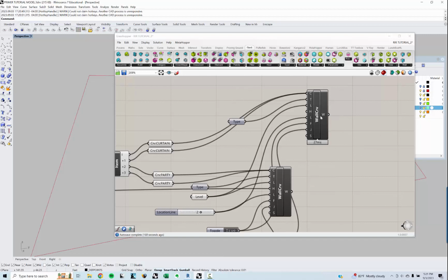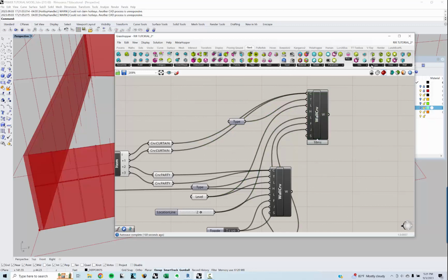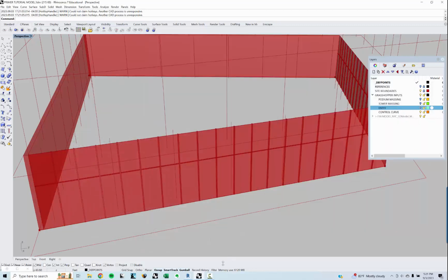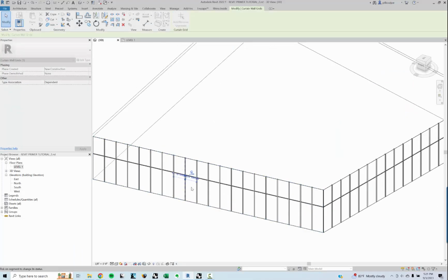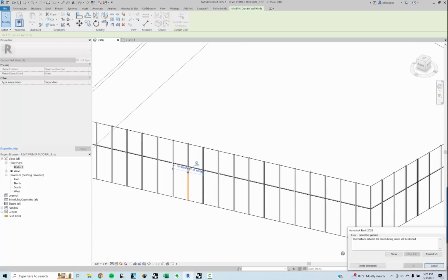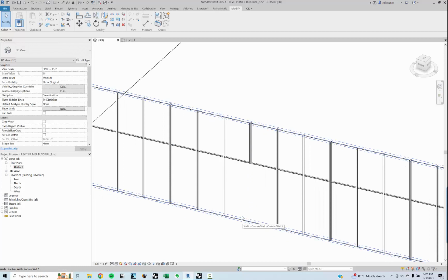Rhino.Inside is updating all these things for me. So once it's set, you might want to turn this tracking mode back to update. So now if I come back into here, I can start making those changes again, adding or removing segments, deleting that element, and now it will stick.